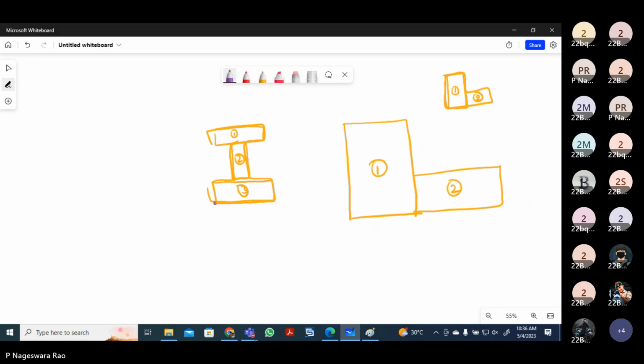Generally assume the bottommost corner as the x-axis and the bottommost corner as the y-axis. Because if the origin is not given, we have to assume the origin. So you apply the standard formula and measure the coordinate of each centroid, C1, C2, C3 in this case. In the case of L, C1, C2. But assume the origin at the bottom when it is not given.